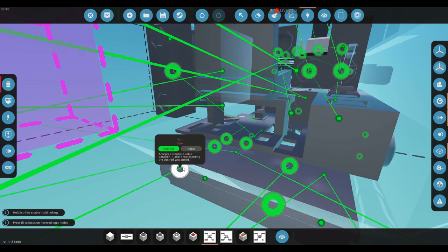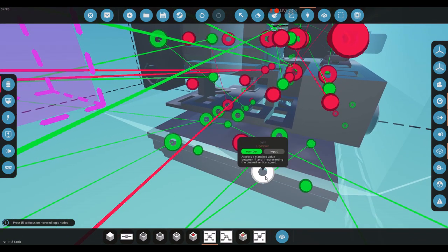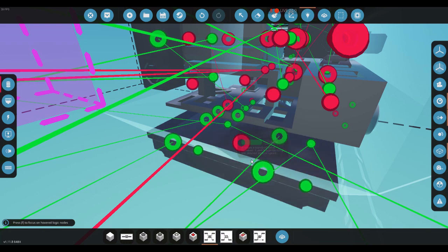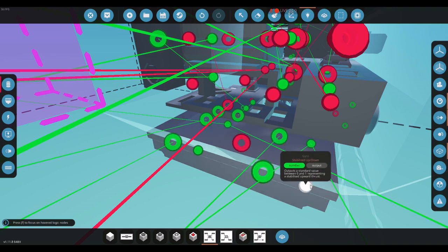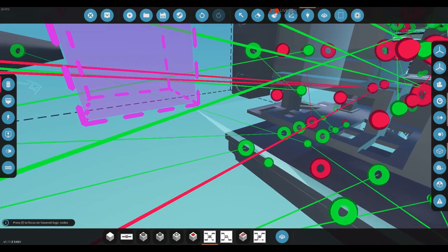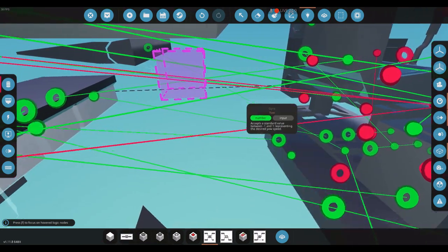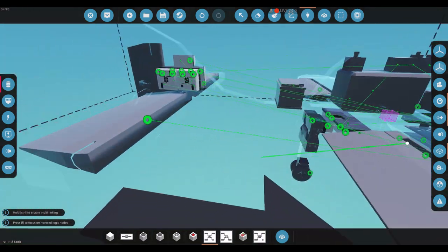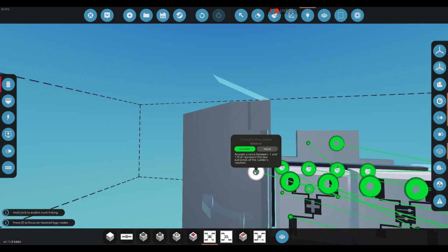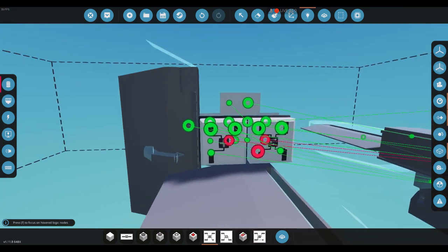Here is our yaw. And then quick note while we are here, because this is an airplane, we do not use the up down on the gyro. The gyro's up down on an airplane for the most part goes completely unused. Many airplane builds I have seen from the workshop completely ignore the up down. All of my planes ignore the up down. You do not need it. So yaw is coming in from the ad block that we just set up. We put stabilized yaw into the rotation of our rudder.